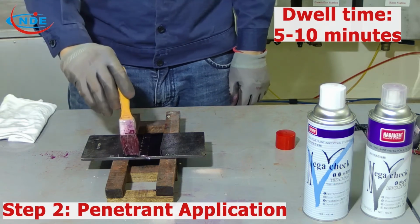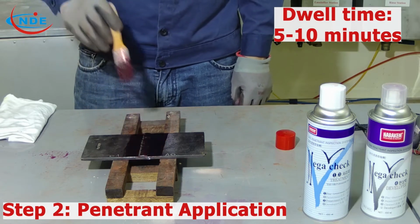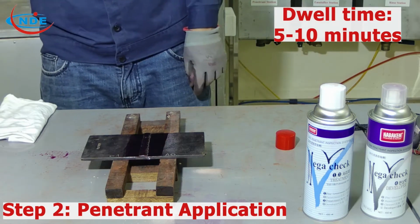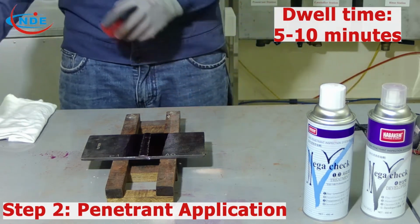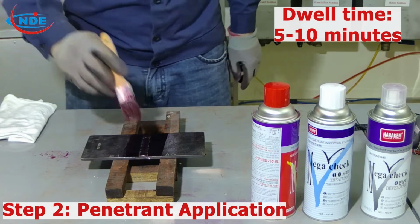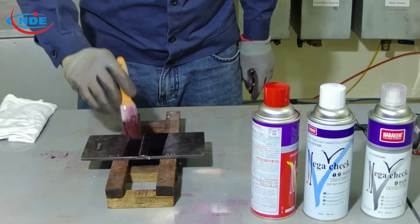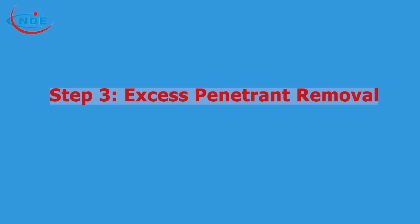The dwell time is about 5 to 10 minutes. Notice that during the penetration time, do not let the penetrant become dry on the surface. We can spray or brush to add more penetrant.